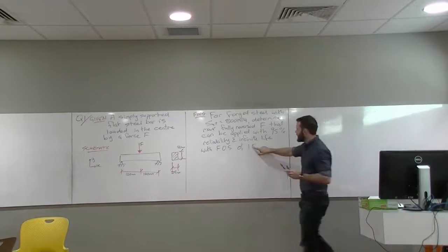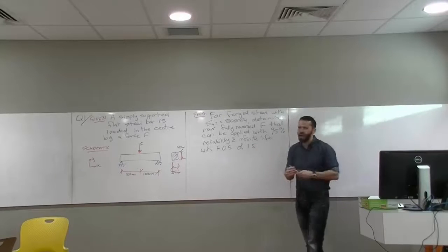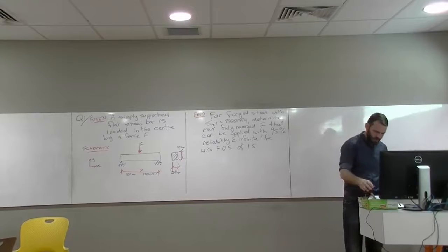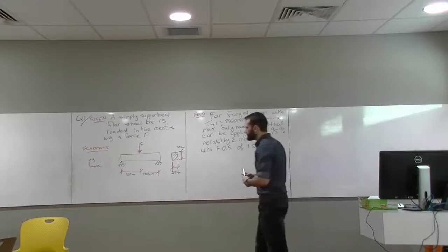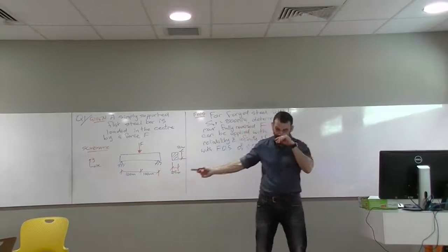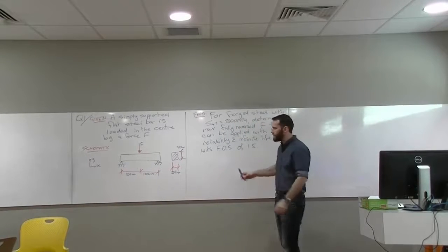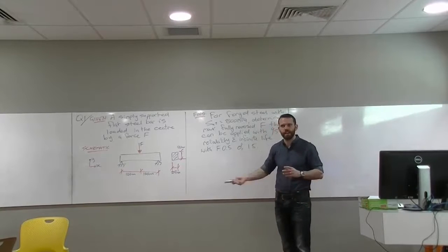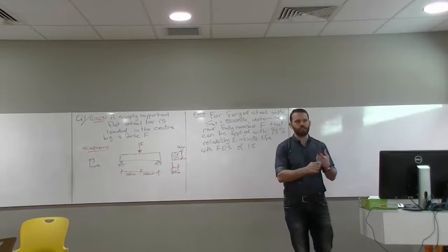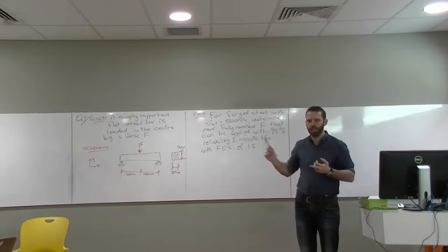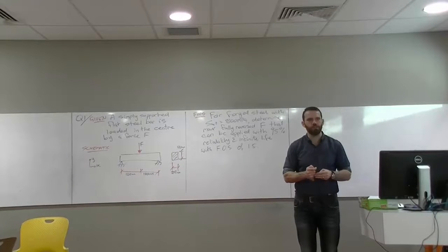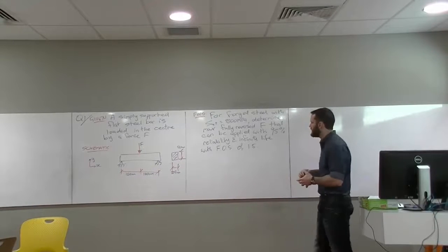So we're getting into the realm of questions that have lots and lots of information in them, and you need to highlight that or at least not miss it. So we have a force, a really simple problem. You guys can smash out some of the forces stuff really quickly. Please put some assumptions after this, lay it out properly. Your assumptions at the very least are your elastic and homogeneous one, your weight negligible one, your transverse shear one. Bare minimum of 3 assumptions at each problem.